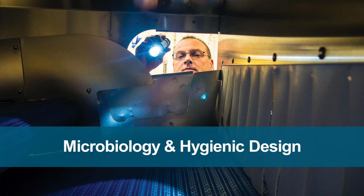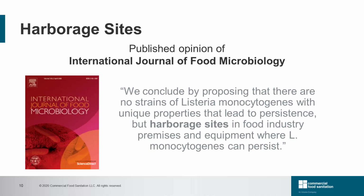Let's look into microbiology and how this relates to hygienic design. The International Journal of Food Microbiology published a study that concluded that there are no strains of Listeria monocytogenes with unique properties that lead to the persistence to cleaning protocols, and that it is the harbor site in food industry premises and equipment where L. mono can persist and grow, pointing out to us that each strain is equally susceptible to cleaning and that we need to focus on areas where the Listeria can be allowed to grow.